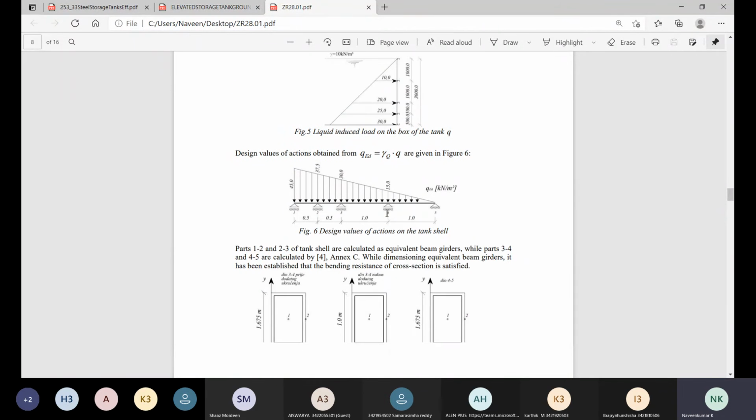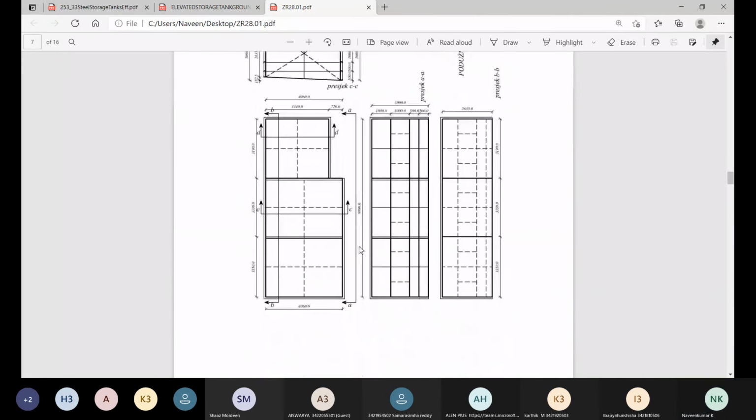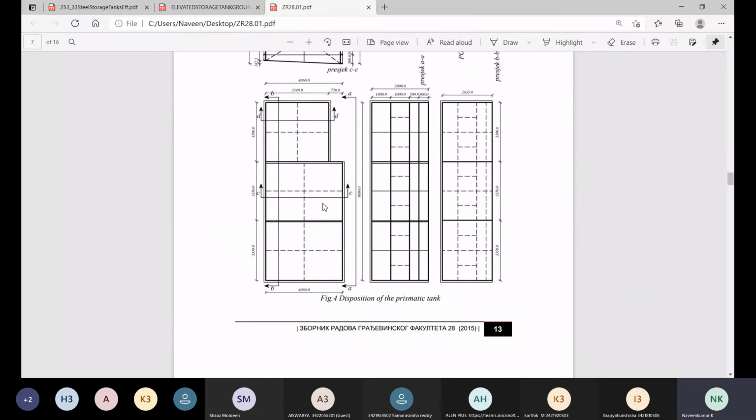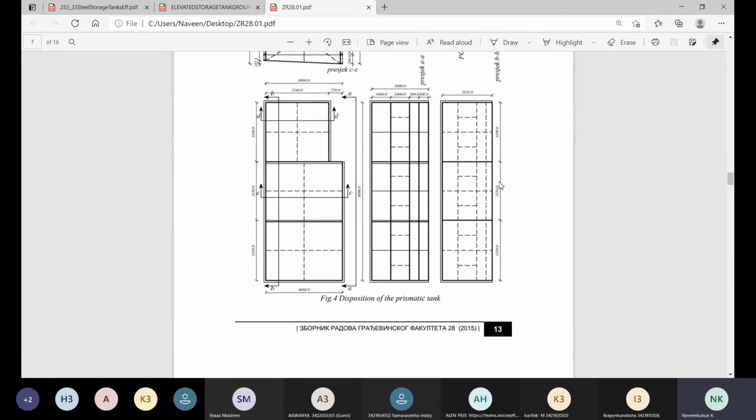So you decide the thickness accordingly. This is the reason it is represented in that way. For example, at the bottom there is maximum thickness. The thickness is represented as the height goes. At the top, the thickness of the steel plate can be reduced wisely, based upon the load intensity. This represents the thickness and this represents the height. The bottom has the maximum thickness and the top has lesser thickness steel plates.